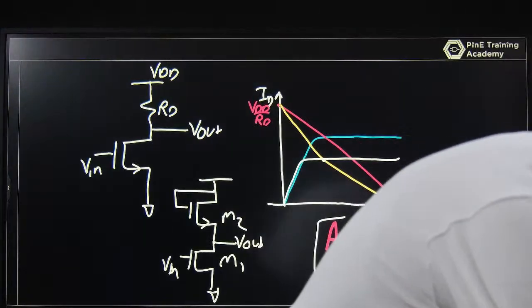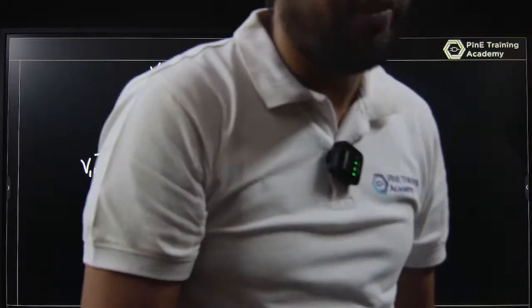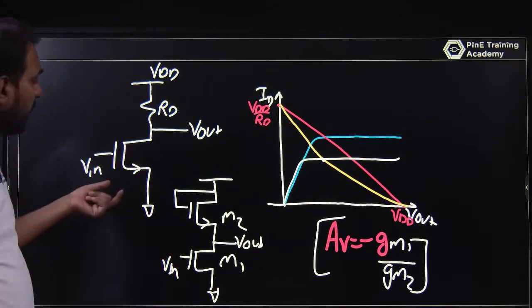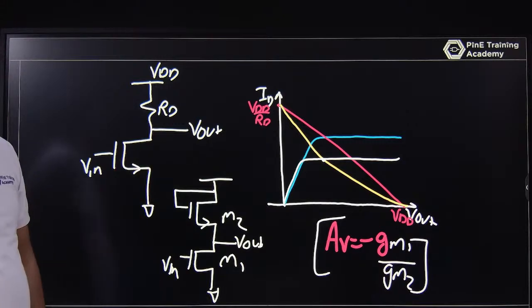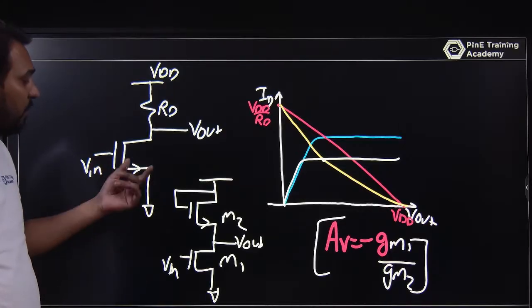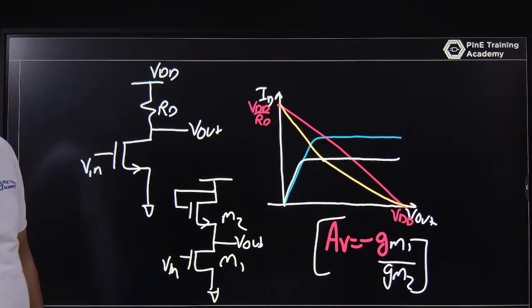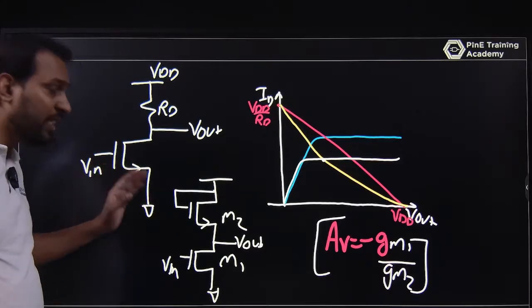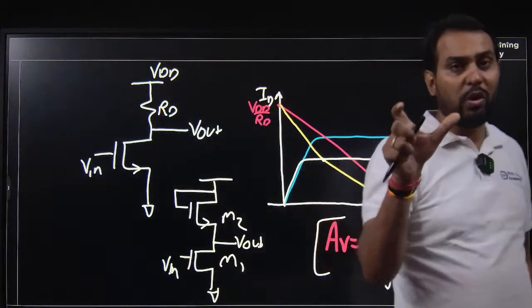Yes, another question. Sir, why is the common source amplifier with a resistor called source degeneration? Source degeneration is a different thing. Source degeneration is not the plain common source amplifier. We use source degeneration when we put a resistance at the source. That is a different part; we will discuss it. This is a common source amplifier. In a common source amplifier with source degeneration, I am using an RS resistance, and that RS resistance behaves like negative feedback. As the gate voltage increases, the source voltage increases, so VGS decreases. The source degenerates to keep the gate-source voltage fixed.